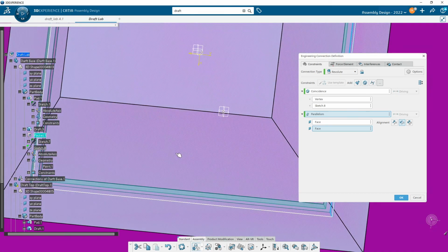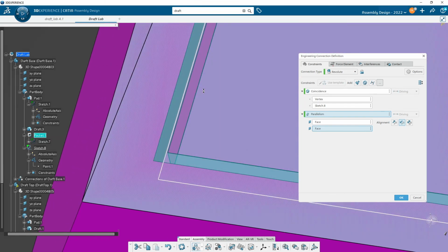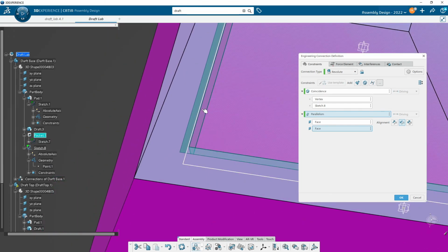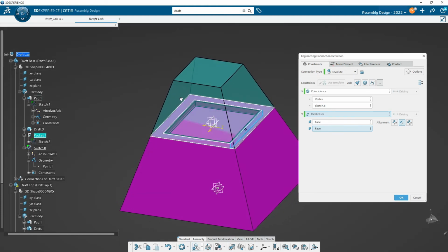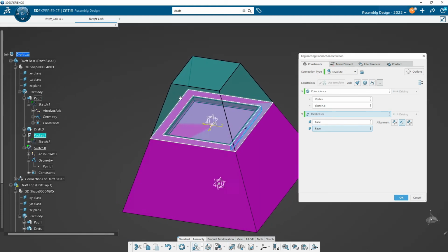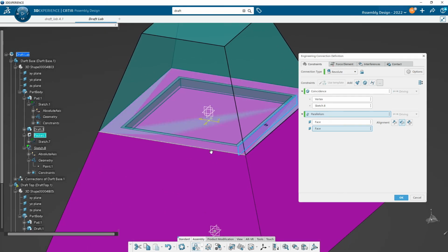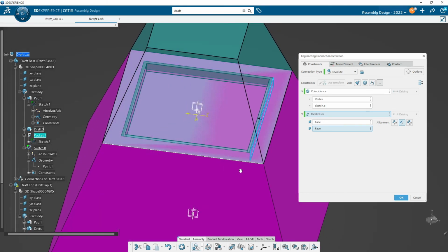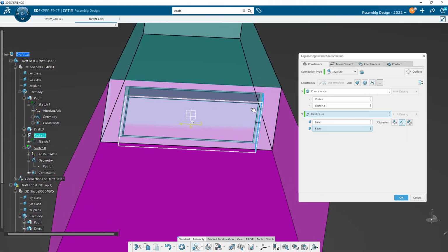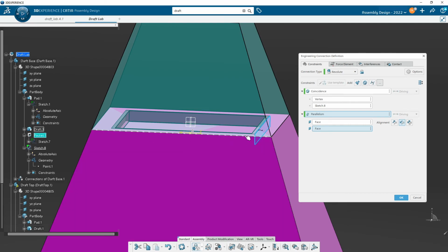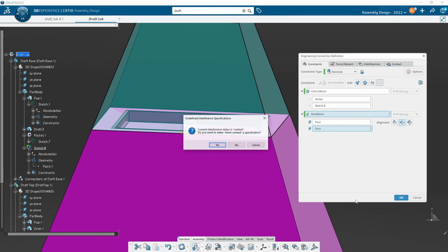And you can see that edge gap that we have. That's a big edge gap, but the thing would fit nicely. And now we're beginning to get a little bit closer to the way real life would be. If you really were to manufacture something like this, we have to have this fitment tolerance. You might even have a situation where one of these is actually tapered. Imagine we actually put a draft on the part that sticks out of this top a little bit. So when you dropped it in here, it kind of wedges in place. You could totally do that.